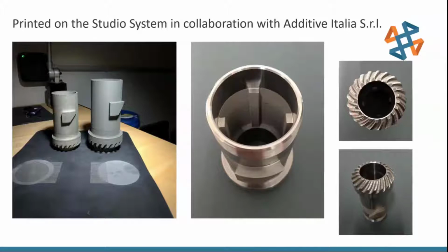The picture on the left there is actually pretty interesting. There is a lot of shrinkage involved when you are sintering metal 3D parts, but this is a pretty well understood situation. This is heavily based off of the metal injection molding industry's technology, and they have been doing this for a lot longer than metal 3D printing has been around. It has very well-defined amounts of shrinkage. You see those two sized parts in that left picture.